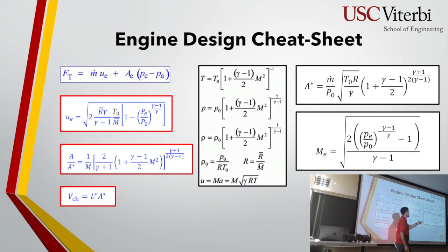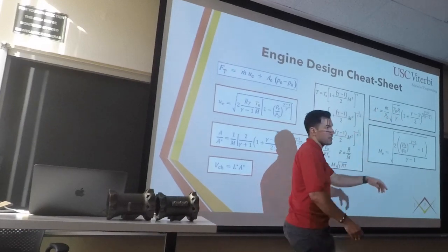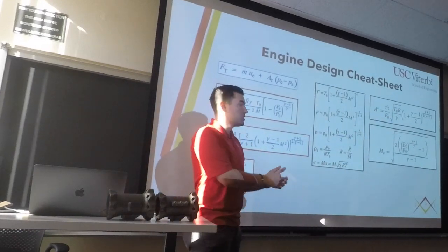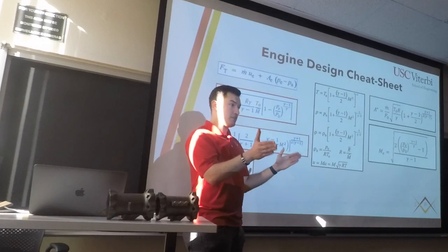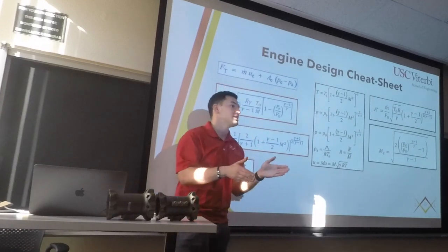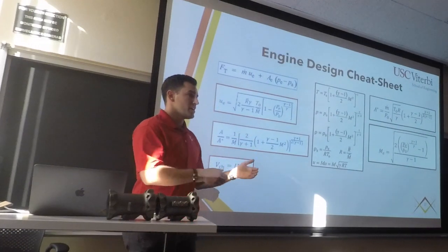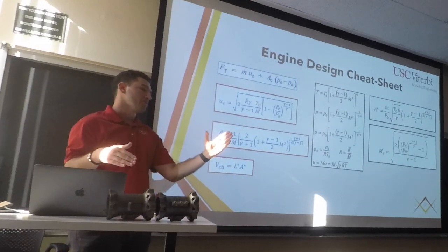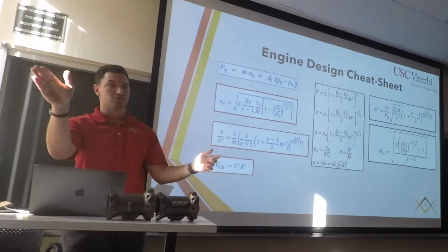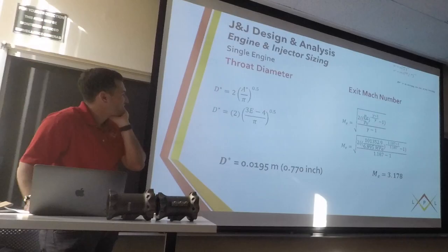And it's half the pressure because we have this, and so if we have this, now this is the same. And so now they could operate at the same throat. The reason why the area at the exit is different is because PE equals PA, right? And so if the chamber pressure is 1,000 and the pressure is slowly going down as you go across, to go from 1,000 to ambient needs a longer nozzle than to go from 500 to ambient. And so then therefore your nozzle's smaller.